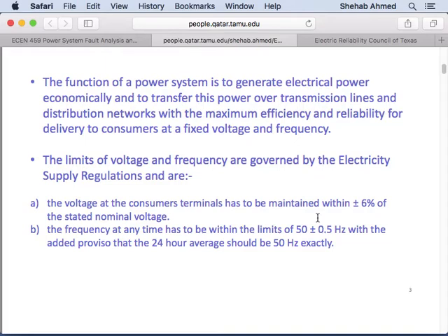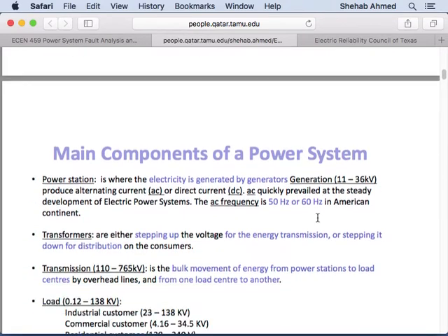So as the frequency increases, the size decreases? The size of all reactive elements decreases with frequency. Capacitors, inductors, transformers, these are all the reactive elements that we have. Motors, too: anything with a reactive component, meaning an L or C in its model. A transformer has an L in its model. A motor has an L in its model. Anything with an L or a C in its equivalent circuit model will reduce in size with frequency, and we will look at that later. So that's the 50 hertz thing, okay?